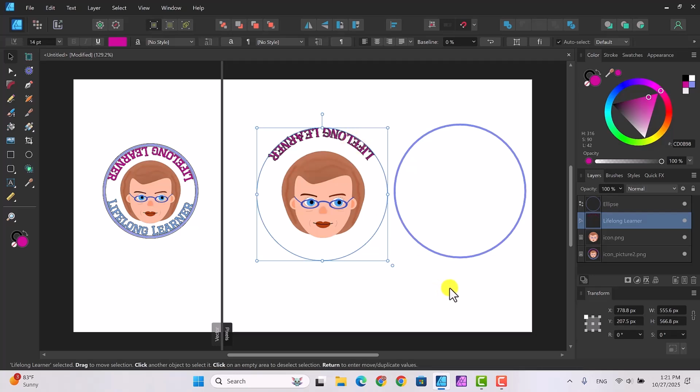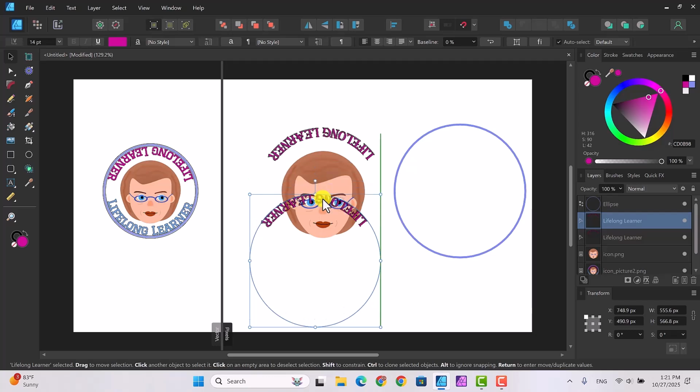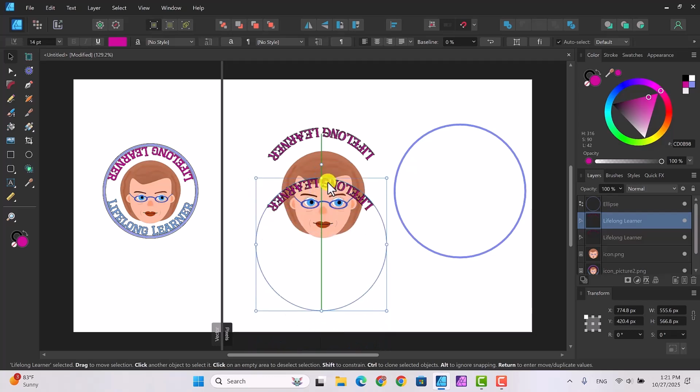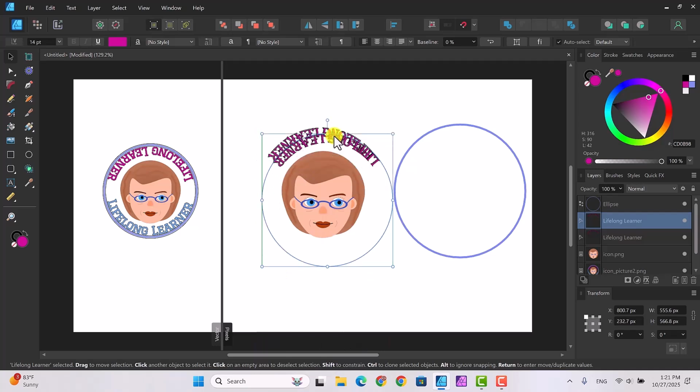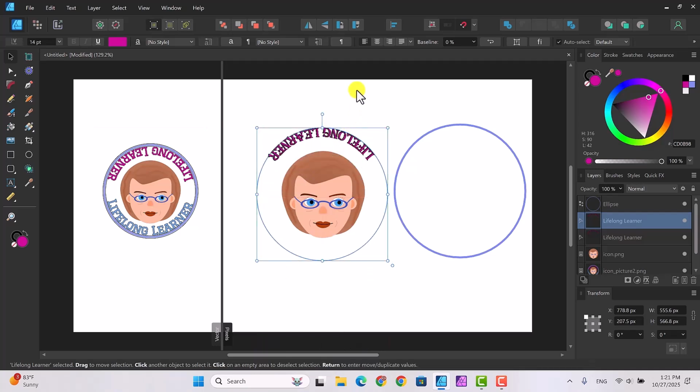So if you make another copy and go Control J, you'll end up with a copy that you can move down, and all you have to do is to flip it like that. So all I really did was I hit flip horizontal, because if you don't flip horizontal, it's going to be backwards. And then I flipped vertical, and I got this down here.